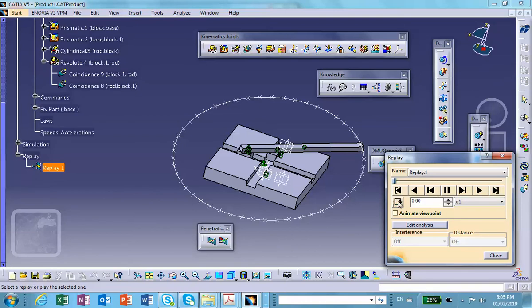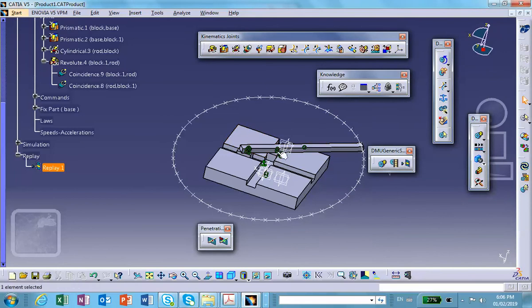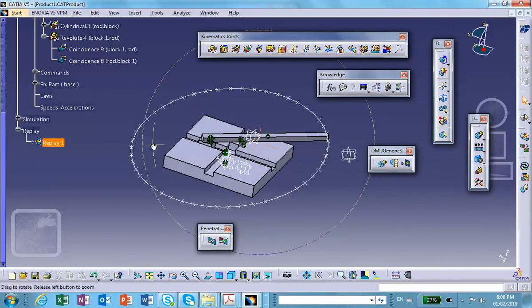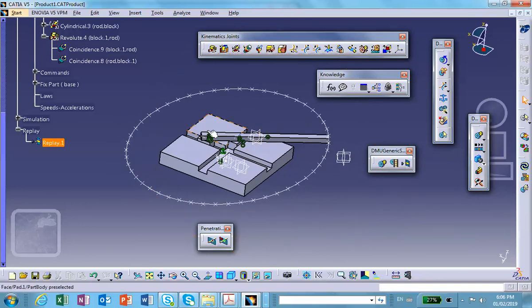So the tip of that rod traverses an ellipse. In the event that the location of this pin, the middle pin, is exactly halfway between the other pin and the end of this rod, then that's going to traverse a circle. Otherwise, it's an ellipse. Now, I didn't put any physics in here, but you can do that yourself, or you really should read the chapter in the book and find out. If you specify the speed of, for example, this revolute joint, let's say that a motor was sitting there, then what is the speed of the point, or create some sensors, etc. So I leave it to you to work it out. Okay, and let's stop this thing. Good luck.